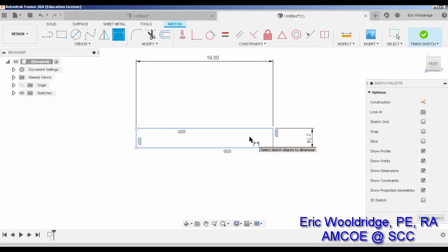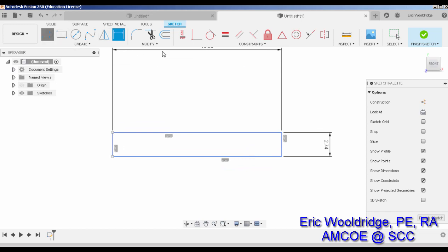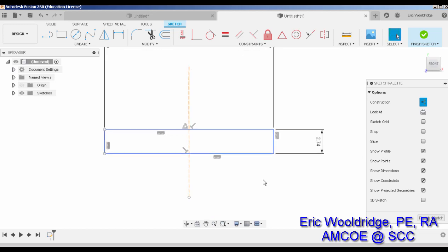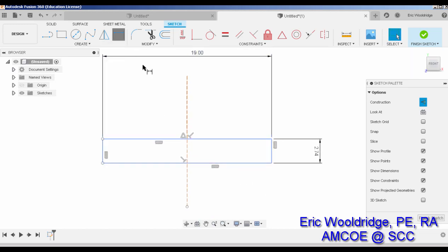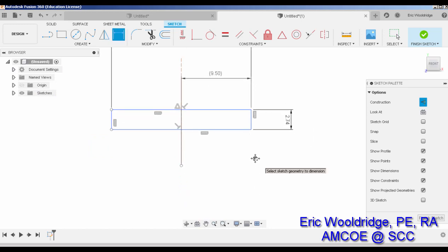Okay, now that we have our box, we're going to create a center line to work with so that we can always track everything. And we'll put it right there. Actually, I'll put it straight up and then straight down. That way we'll be able to lock on to it periodically. And I'll even add a dimension so that I can keep track to make sure it doesn't move. And looks like we're going to hold it 19.5, and that's what we should be seeing.